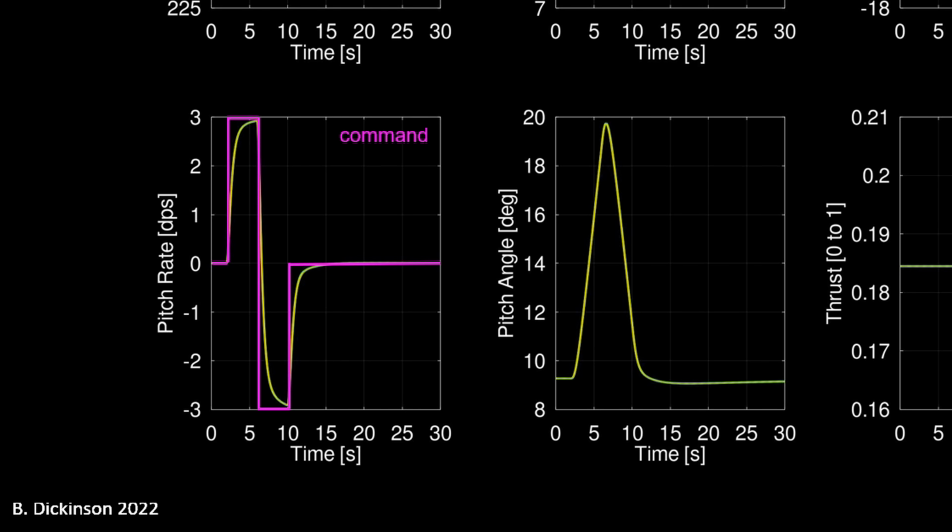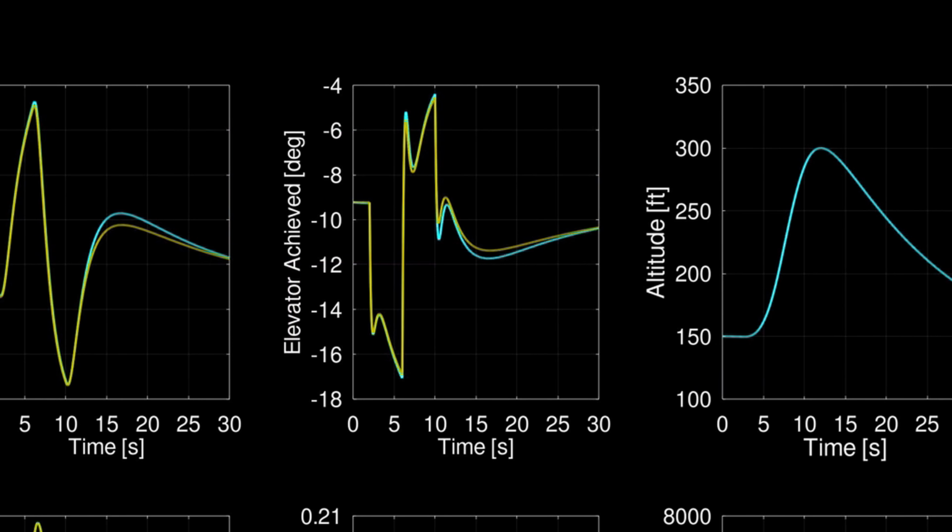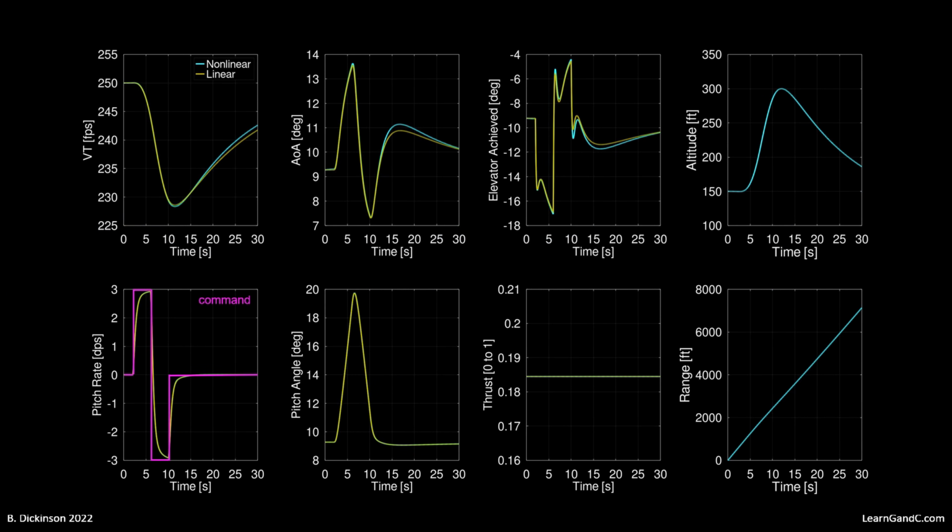Pitch angle linearly increases to 20 degrees, then nearly returns to the trim condition without oscillation. The faster actuator enabled autopilot tuning for improved closed-loop performance, specifically rapid tracking that's appropriately damped, and by inspection, no phugoid coupling into the pitch rate and pitch angle response.